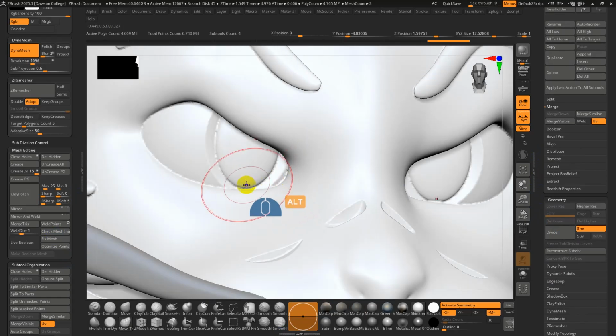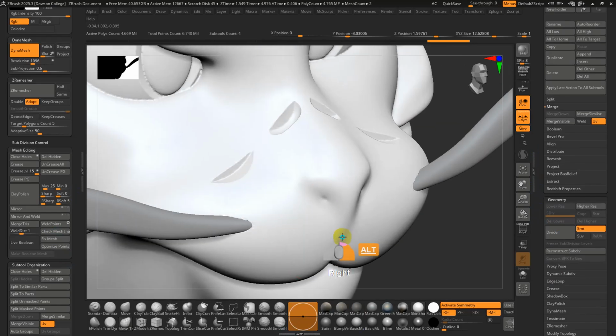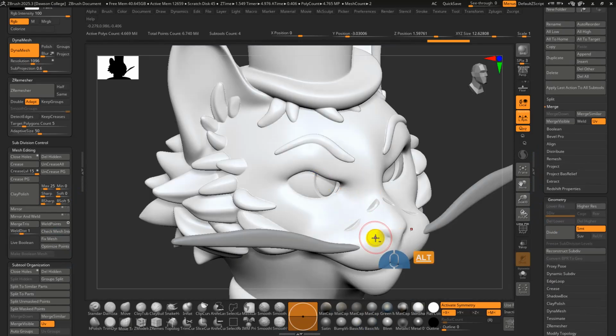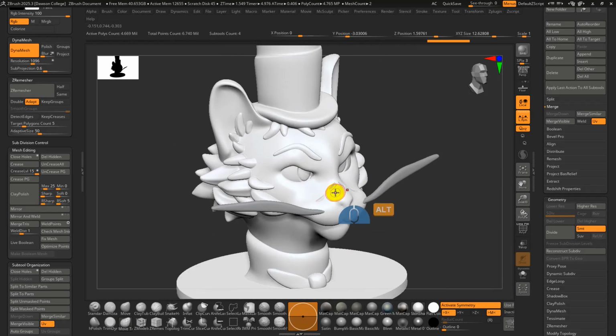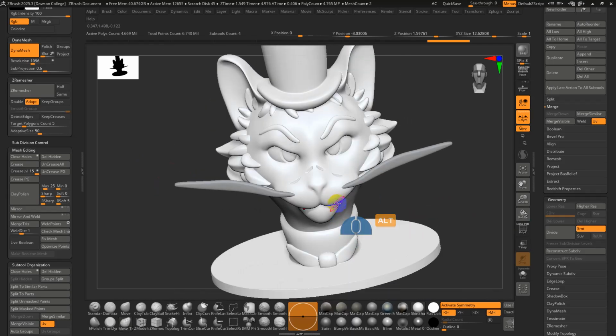And this time, with project turned off, I don't have any issues with it jumping across little cavities. And even if it looks a little bit gritty, just remember that this thing is going to print at a size that's going to be kind of like this. So you won't even see some of that roughness in there, okay? Now again, I mentioned this before. The issue with this is that the poly count is quite high for the slicing software.